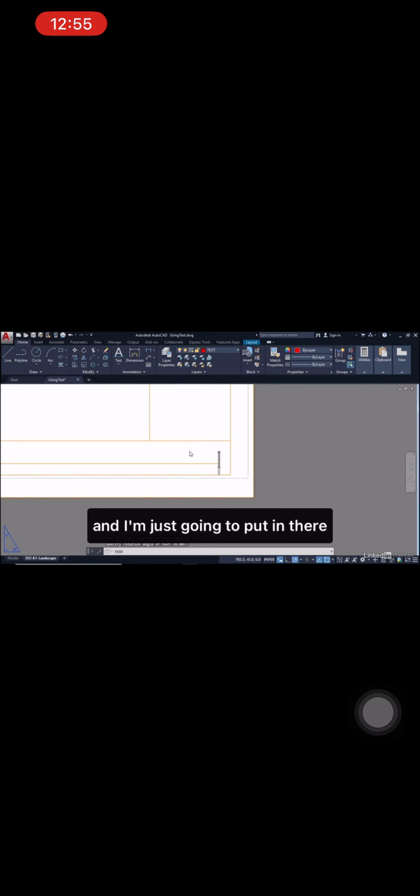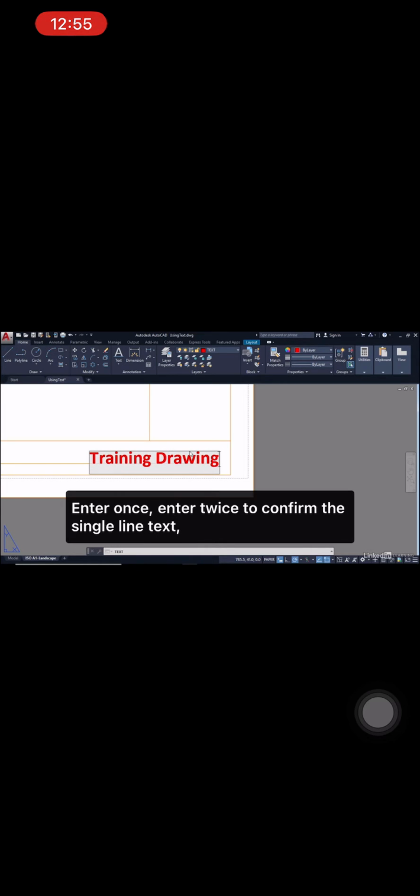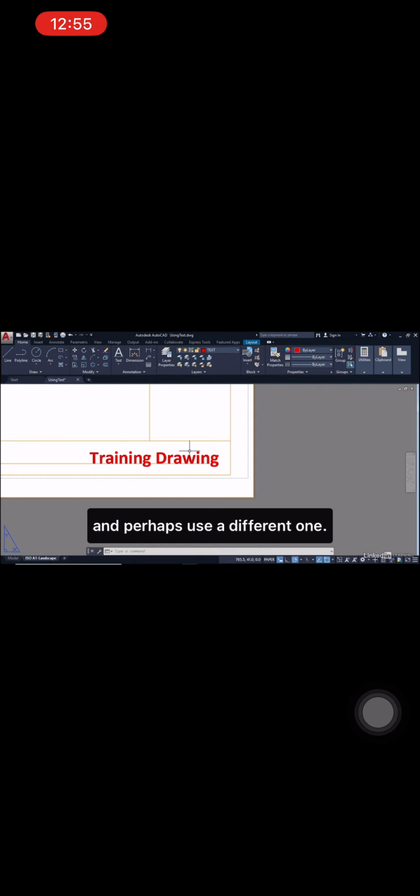And I'm just going to put in there training drawing, like so. Enter once, enter twice to confirm the single line text. And again, that's using that particular text style. Again, you can experiment with text styles and perhaps use a different one.